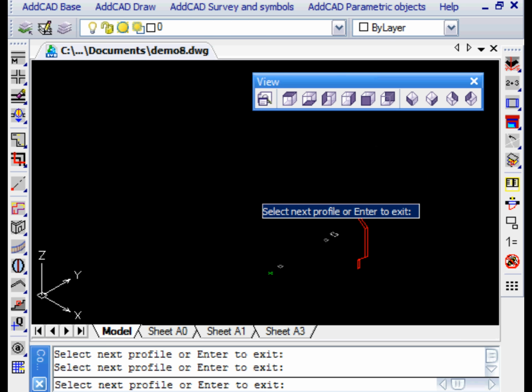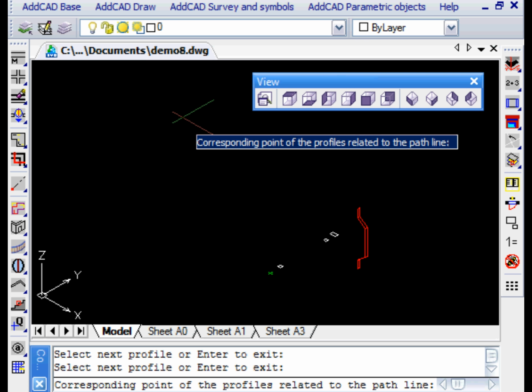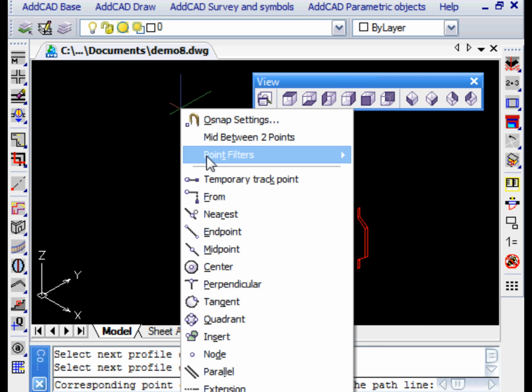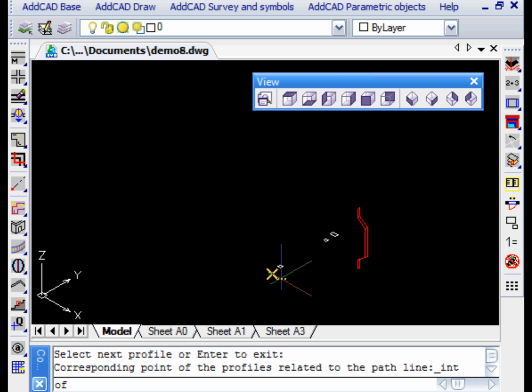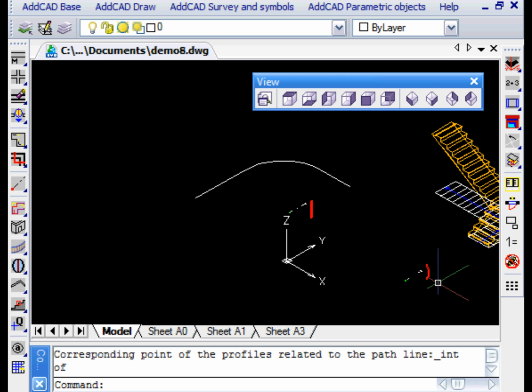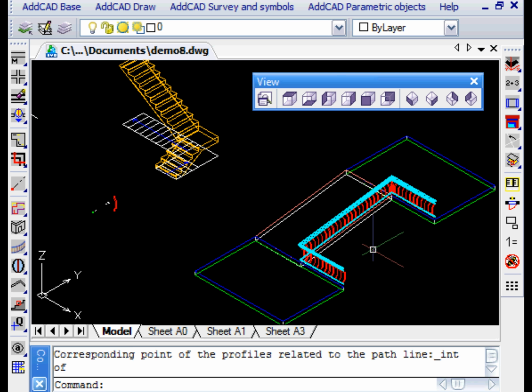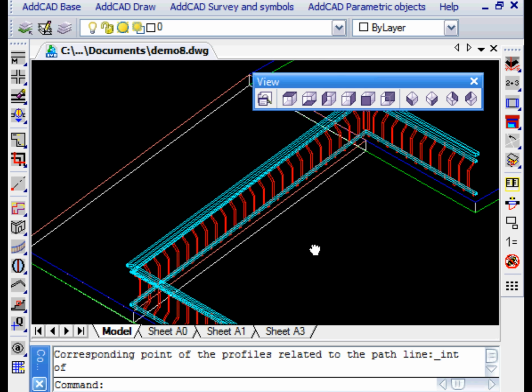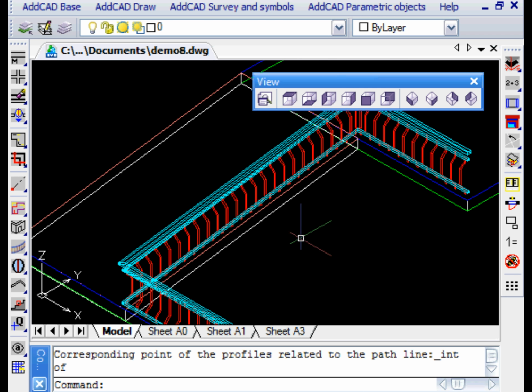We are then asked to select the profiles to generate along the contour of the railing and a reference point. This point, as we guess, is the point that will ensure a correct positioning of the profiles with respect to the contour. For the library blocks, the recommended point is the crossover point between the 2 green lines.